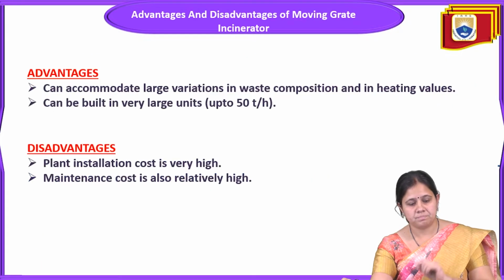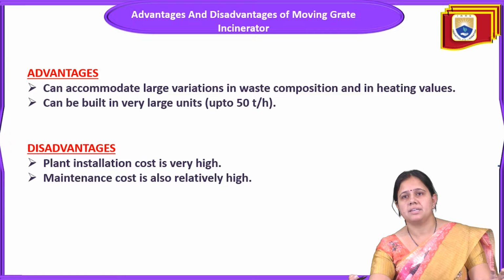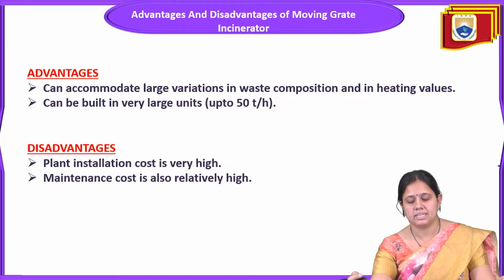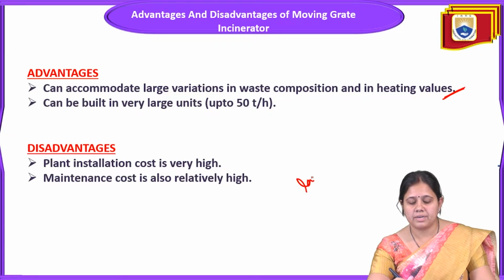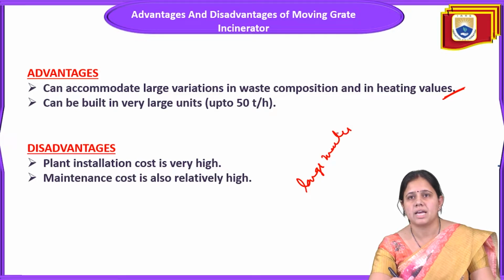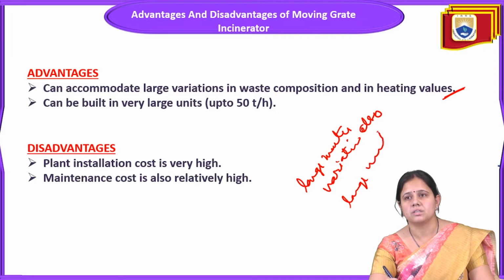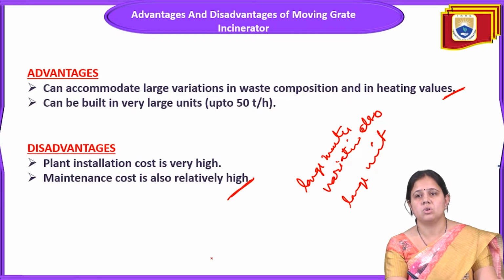Now these are the advantages and disadvantages associated with this moving grate incinerator. The advantage is that it can accommodate large variation in waste composition and in heating value, and it can be built in very large units. The disadvantages are that the plant's installation cost is high and the maintenance cost is also relatively high. So it is not cost effective.